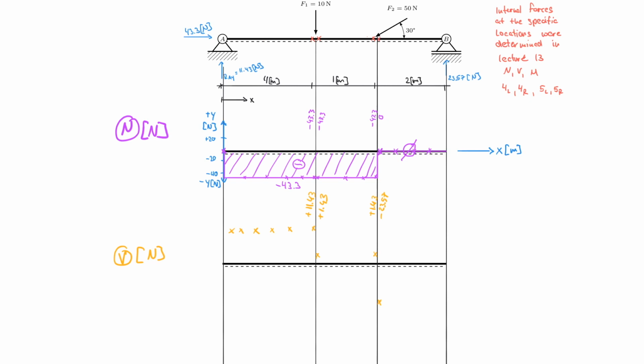Now take a look at the equation for the shear force that you prepared for this location here for 4.00001, and then compare it to the equation that you wrote down for 4.99999 at this location. And what you will find is that the length here, the 1 meter, also does not contribute or does not play a role in that particular equation. This will be different later, so be careful with that. But hopefully you see that you could have graphed the value here, here, here, and so on and so forth.